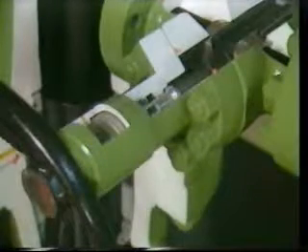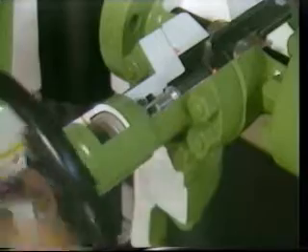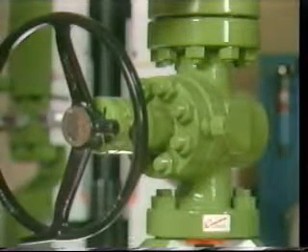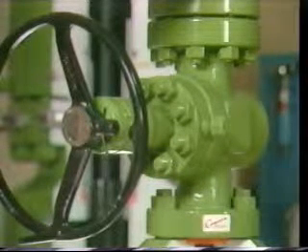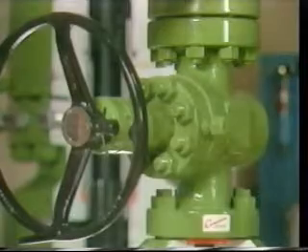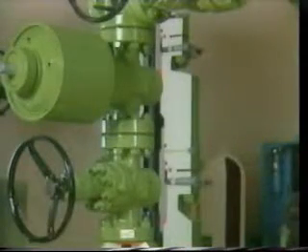Gate valves are full opening valves that are opened or closed depending on the position of the steel gate. This gate has an opening that allows fluid to pass unhindered through the valve body when the openings are aligned. The gate valve is considered the primary flow control at the wellhead and must be operated fully opened or closed. Christmas trees always have one gate valve called the master valve, and commonly two are used.